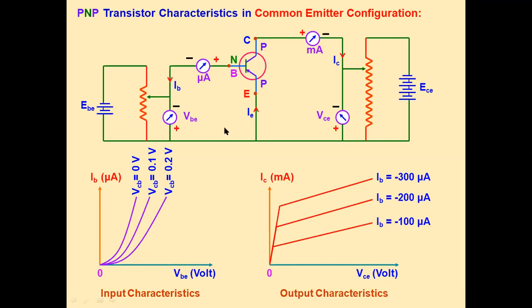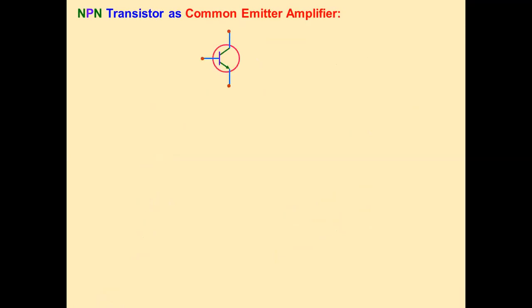When you see carefully, the output characteristics get divided into 3 regions. One is known as the cutoff region, meaning when both diodes, the emitter diode and collector diode, are reverse biased, the current is equal to 0. In the second case, when both the junctions are in forward biasing, this is the saturation region. And when the transistor is in forward and reverse biasing, the collector current remains slightly constant, and this is known as the active region. So this is the IV characteristics of the transistor in CE configuration.